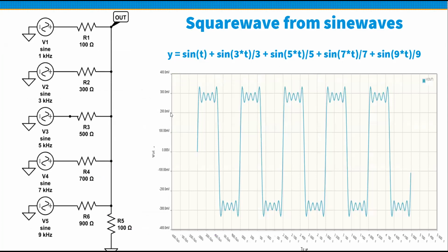How you burn up your audio driver. But also how you can recreate a square wave by adding up all of the odd harmonics in this series, where you take the third harmonic with an amplitude of 1/3 and the fifth as 1/5 and so on and so forth. Even only doing that many, you can see how it's a square wave with ripple on the top. So the more additional harmonics that you put in there, that would eventually make that into a perfect square wave if you had an infinite number of harmonics.